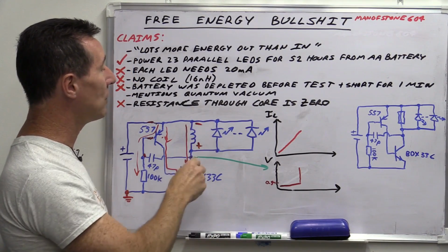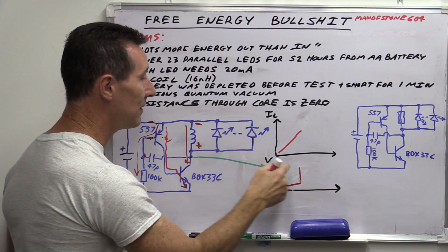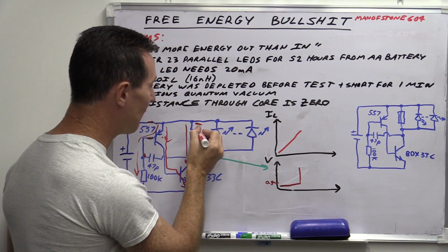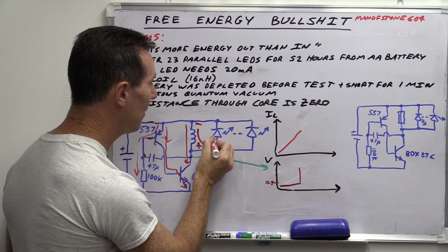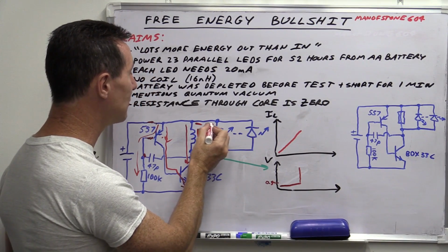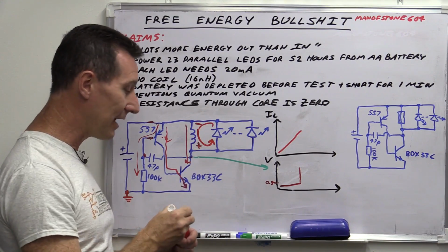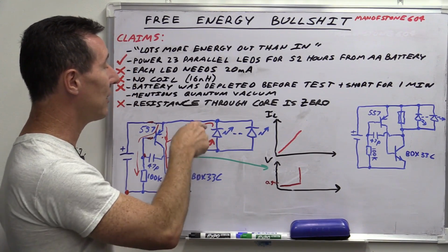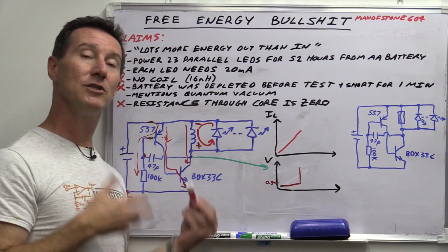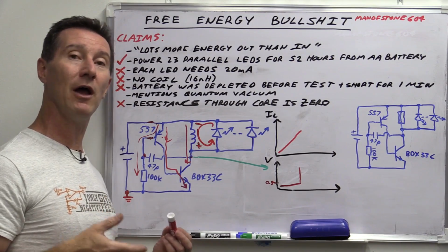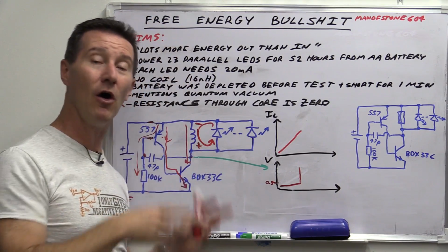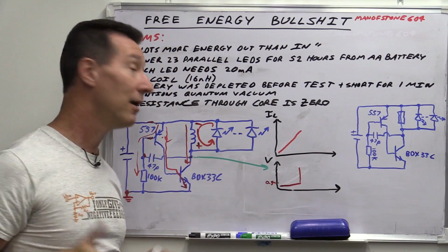It clamps that voltage across there, and so when this thing collapses, voltage has gone up to this point, and we're going to have current flow now. Where's it going to go? The only place for it to go is through our diode and around like that. So we're going to have a huge spike of current in the diode. And of course, it's going to clamp it to basically the forward voltage of the diode. But if we didn't have the diode here, then the voltage at this point could get very high, tens of volts or whatever it happens to be.